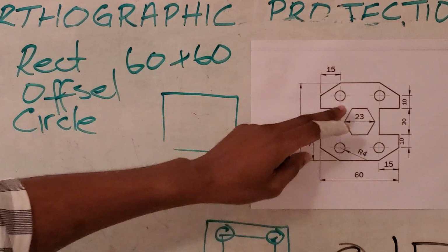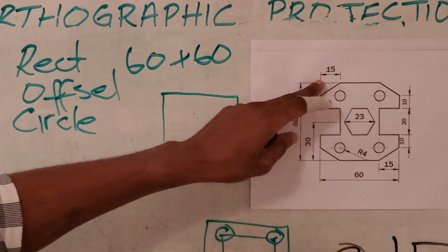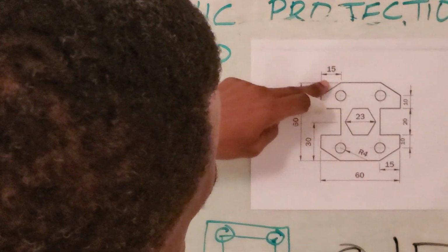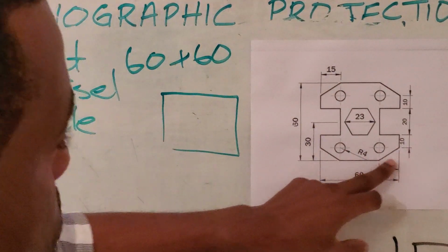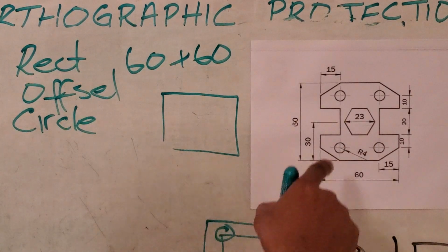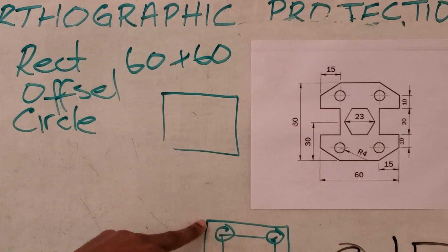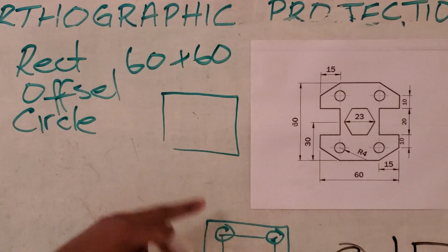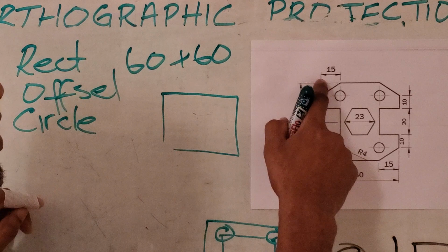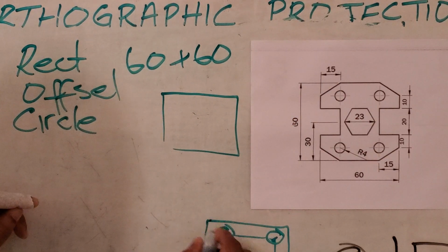Now our next step is to chamfer these edges. These are 15 in this direction. Probably what I would do is use chamfer. Well, we could do it one of two ways. We could use circle to mark this, or use object snap tracking.